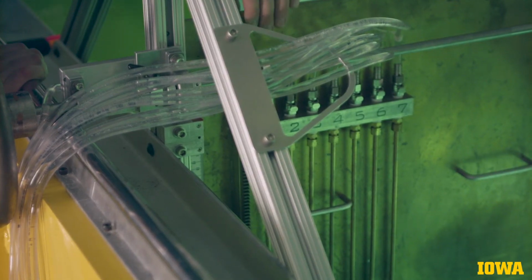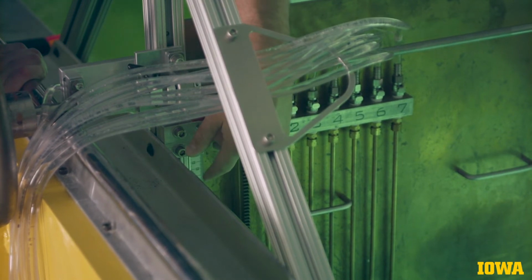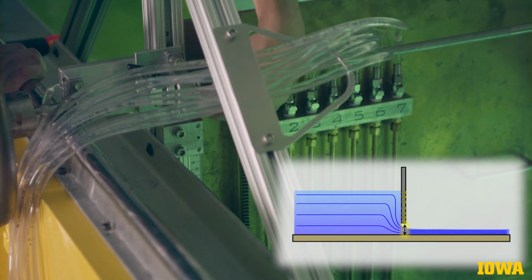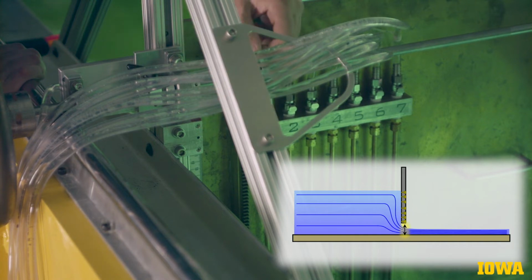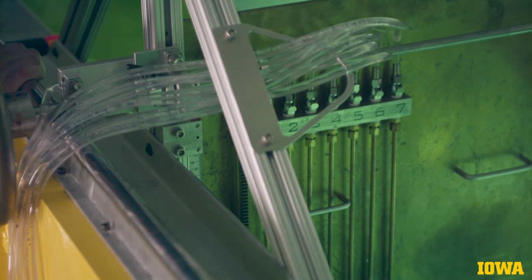So shown on the back of the gate here are 2 important things. The first is the linear rule, which is adhered vertically to the back of the gate, which we use to measure the size of the opening at the bottom of the gate. The location of the top of this block lines up with the linear rule at 5 centimeters currently, indicating that there's a 5 centimeter gap beneath the floor of the flow channel and the bottom of the gate.